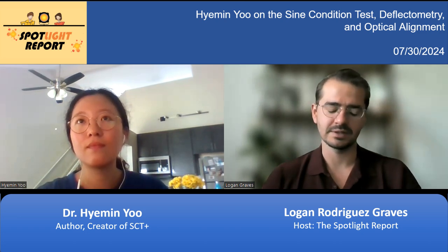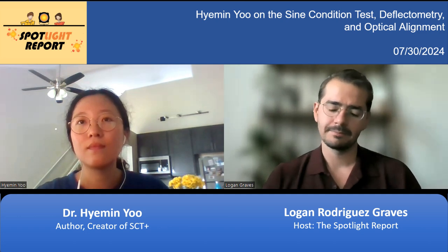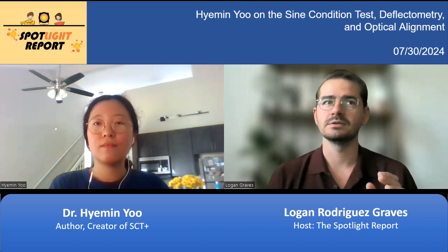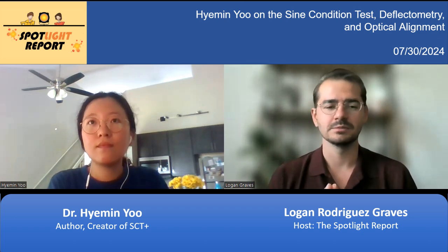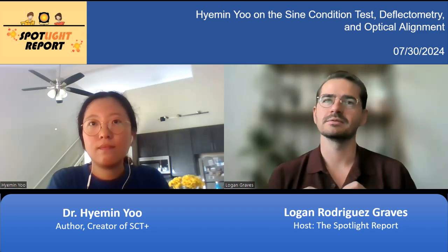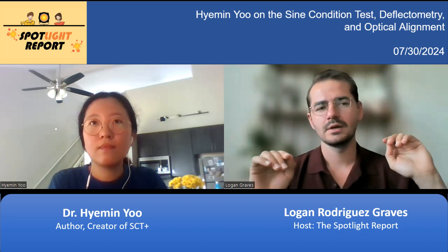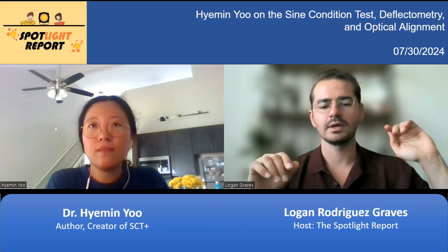You basically do a deflectometry setup. You expand it as well such that you could do this setup for a reflective system, so a more traditional deflectometry setup. And actually, let me add something here for listeners. In deflectometry, you typically have a camera, you have a source, and you're going to display. You're going to emit light from your source at some known point. Rays will leave that. It'll hit a test optic.